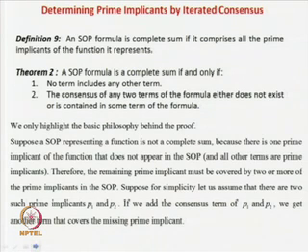You take pairwise terms, do not open it up, take an SOP formula or SOP Boolean expression, whatever expression is given to you, and then you go for pairwise term consensus. It is very important to note that we are not going for a canonical expression form. We are just taking these terms in whatever order they are, so that will be smaller, if you remember. We will see with an example also.